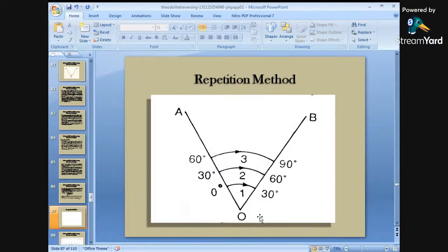Now focusing of your eyepiece, focusing of your theodolite. What you need to do is fix the lower clamp and release the upper clamp, and you have to make the vernier exactly at zero. So the reading on the vernier A should be zero, and at vernier B it should be exactly 180 degrees.